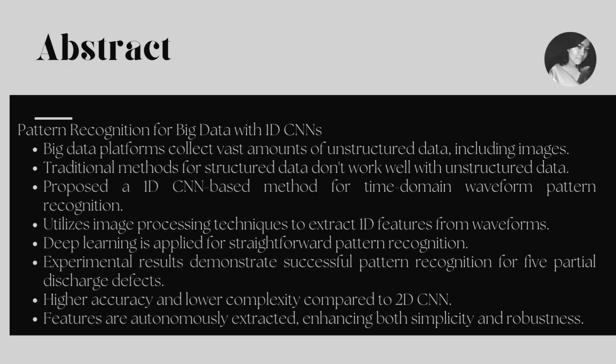Big data platforms and centers which store unstructured data like images are everywhere. The partial discharge pattern recognition method has been extensively studied for structured data, but traditional methods can't be applied to unstructured data. To this end, a one-dimensional CNN-based time-domain waveform pattern recognition was proposed.